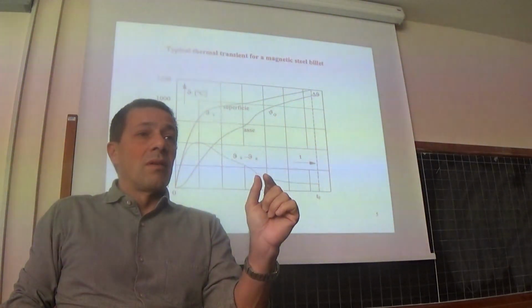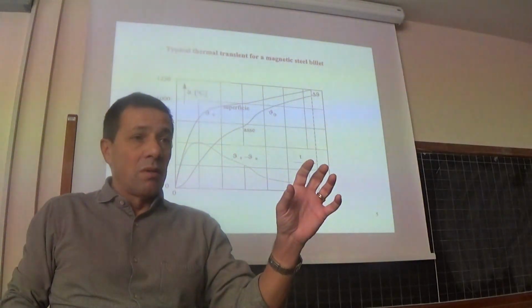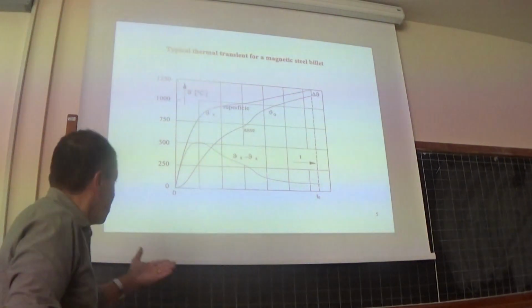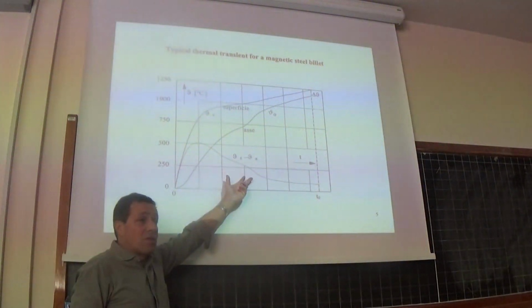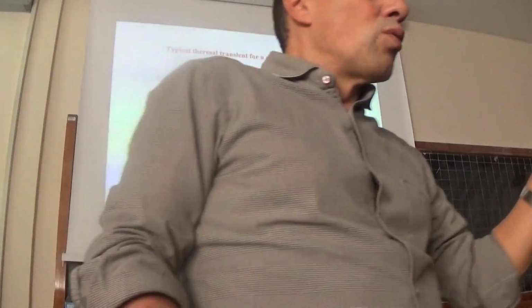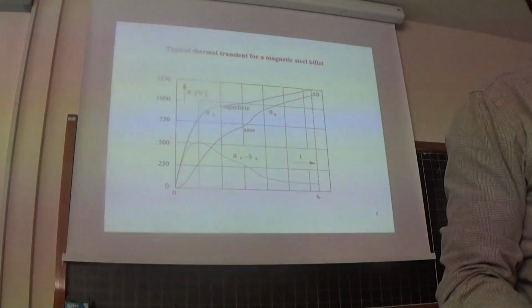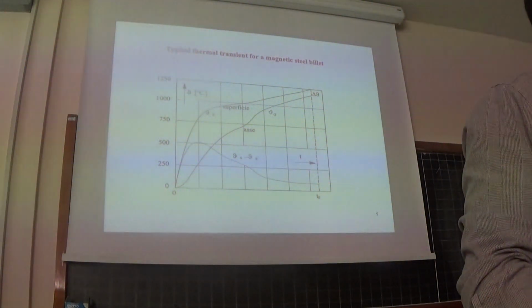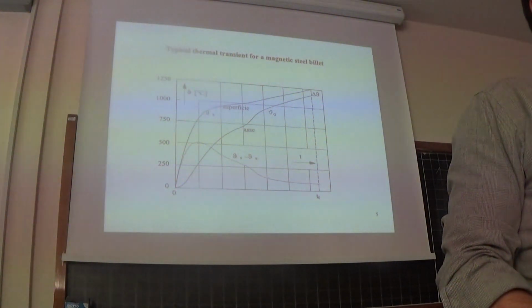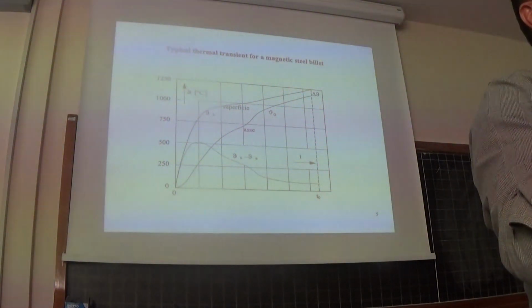It means that the temperature increase on the surface is much more than the temperature increase in the axis. So this is the behavior of the temperature difference, and during induction through heating we have to take into account this temperature difference, and we must be able to control it properly, because if this temperature difference is too high, we can create some cracks in the billet.